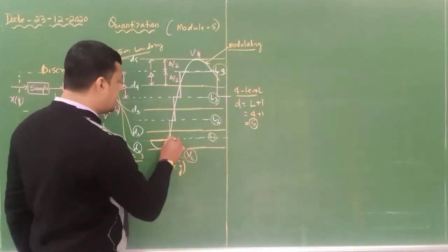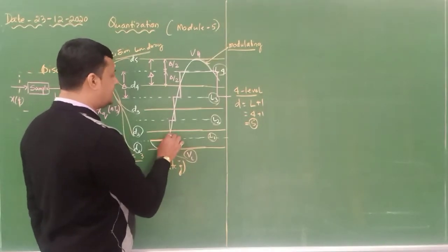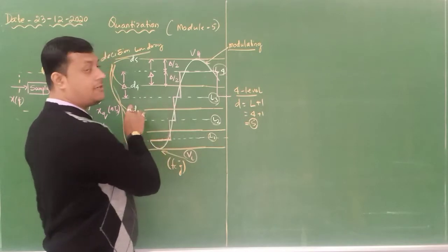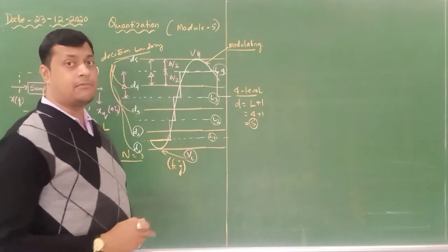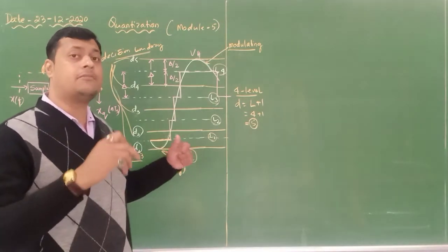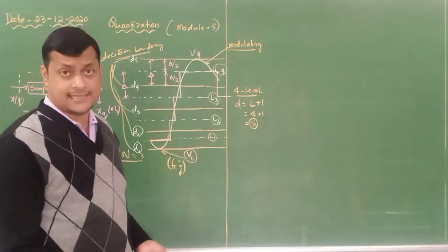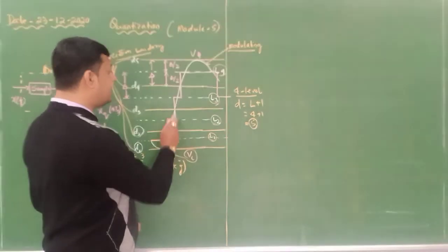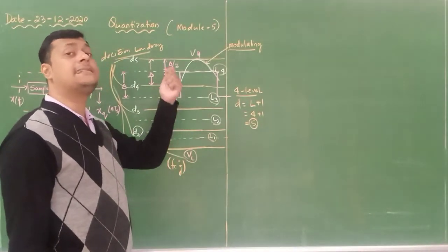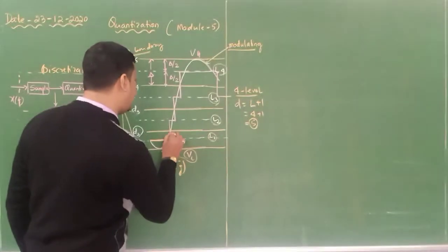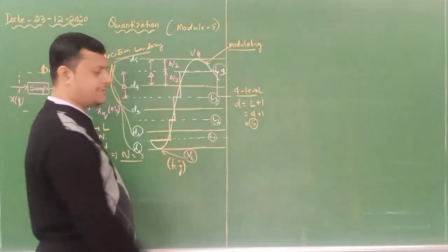Now once this level is identified, next the signal is entering decision boundary 3. Okay. So now when it is entering decision boundary 3, the quantizer will jump to the next level as the signal is entering the decision boundary. So it will enter the second level like this.